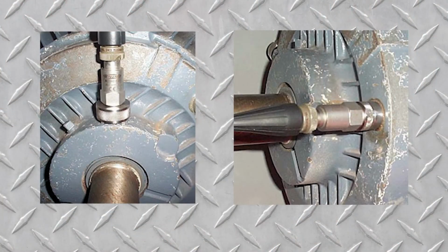Here are a couple of vibration sensors that are attached at a couple of points on a motor. One sensor is aligned on the rotation axis, and the other is perpendicular to the rotation axis. These sensors are typically attached magnetically and can come with either flat or rounded mountings. You can put them on a number of different motors, moving them around, and they're very inexpensive.